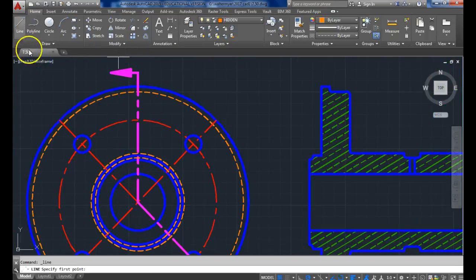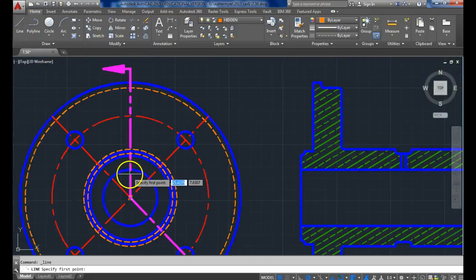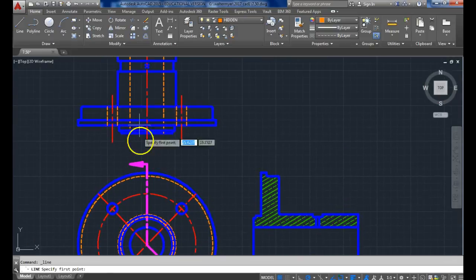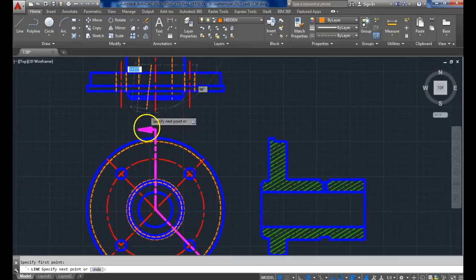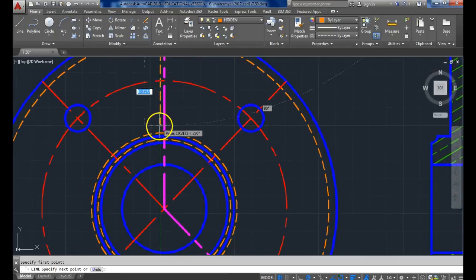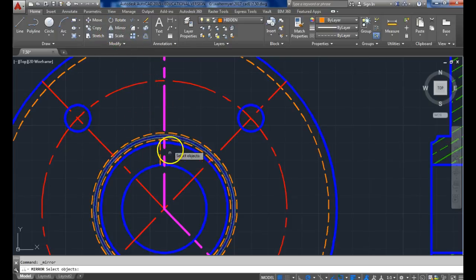And then hidden lines are going to go, and they're going to get caught on all these other little lines, so I'm going to leave it attached. It's going to go from the circle I just brought over all the way down to the inside. Delete that line. Again, symmetrical, select it.